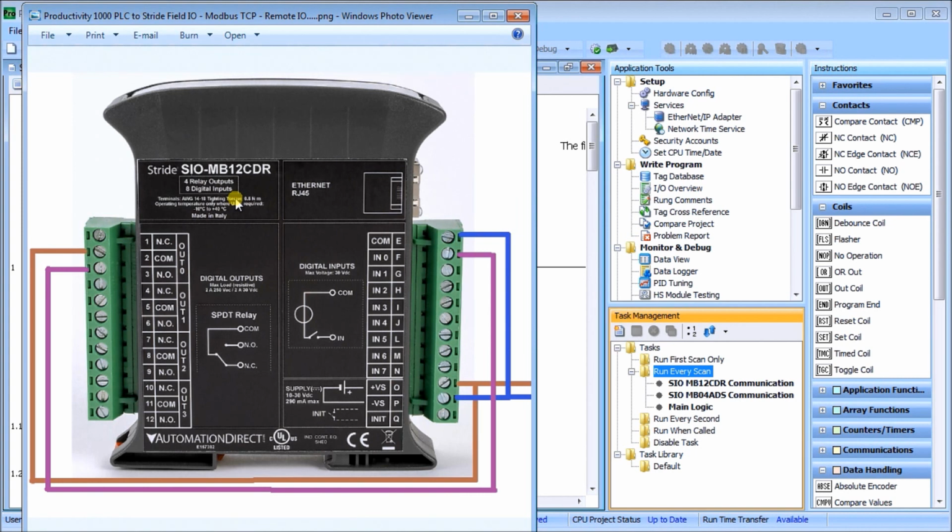and it is, like we said before, a Modbus TCP server. What we're going to do is take our output and feed that back into our input here. We have a 24 volt power supply to supply this voltage. My plus voltage comes in this connector here at BS0, and it's a brown wire right here.